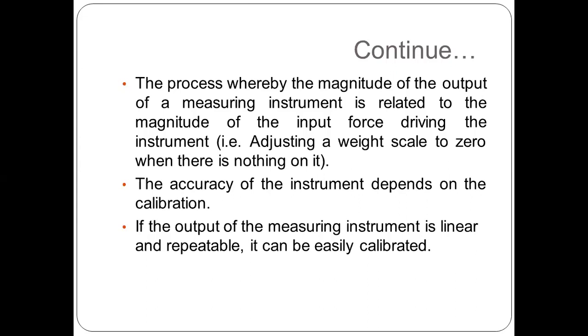The best example for calibration is when you go to the petrol pump for filling petrol or diesel. Every time after filling fuel in a vehicle, they again press zero, which means they are setting it to the zero value. Suppose they are not pressing zero, then what happens? The reading will continue from the point where it stopped.